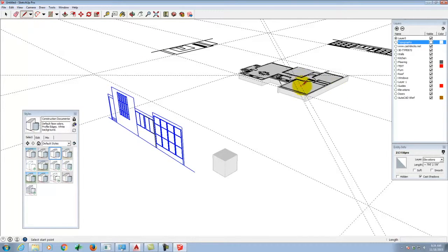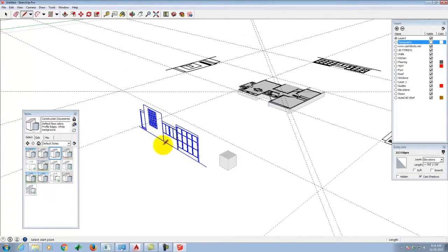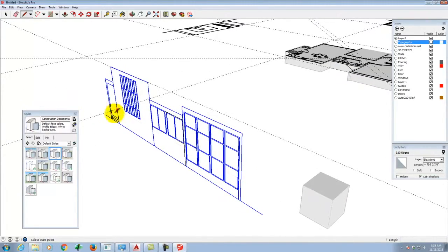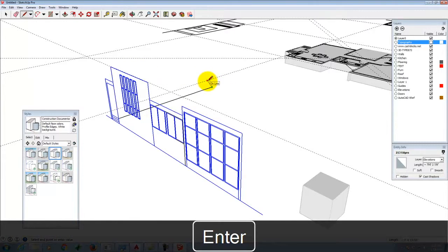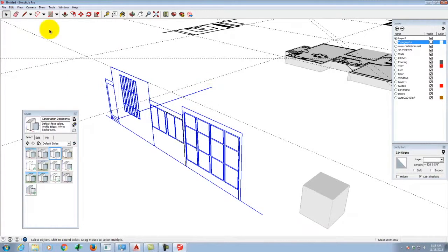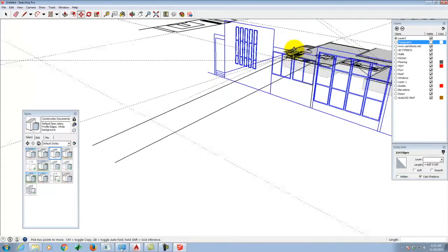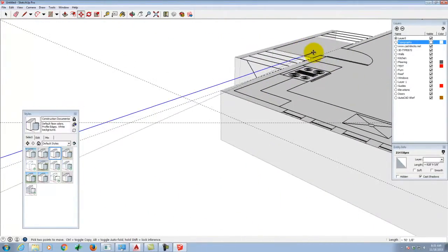And now I need to move it so that it's oriented correctly with this building over here. Okay? So I know that the bottom floor of my building lines up with this step. It also would line up with the bottom of this window because these are floor-to-ceiling windows. So depending on where, I think the step is probably the easiest reference point. Excuse me. I'm going to draw a line that just sticks out. And then I'm going to move with the line and the object here. I'm going to move this over so that it snaps to where that point is.